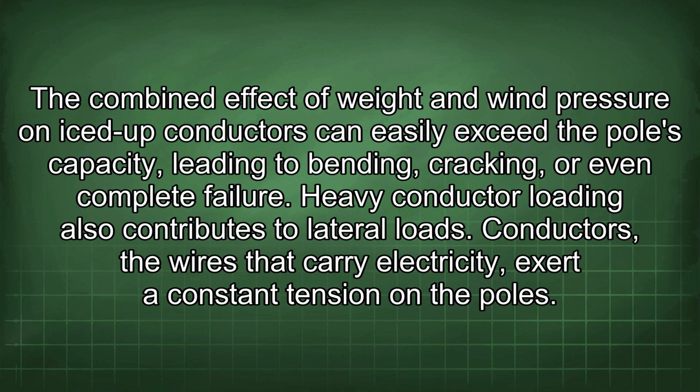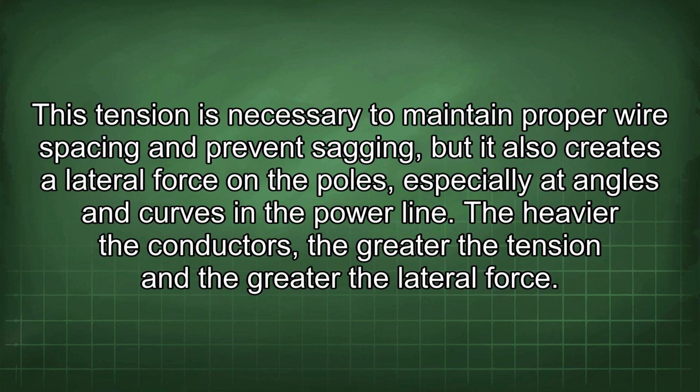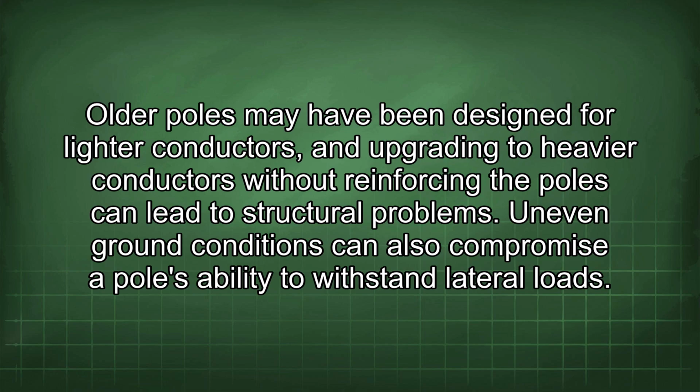Heavy conductor loading also contributes to lateral loads. Conductors, the wires that carry electricity, exert a constant tension on the poles. This tension is necessary to maintain proper wire spacing and prevent sagging, but it also creates a lateral force on the poles, especially at angles and curves in the power line. The heavier the conductors, the greater the tension and the greater the lateral force. Older poles may have been designed for lighter conductors, and upgrading to heavier conductors without reinforcing the poles can lead to structural problems.